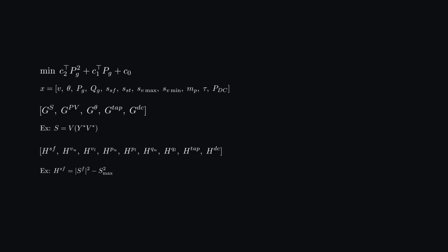By modeling both the active and reactive effects, the ACOPF provides a more realistic picture of system behavior. It can identify when voltage or reactive constraints become the true bottlenecks. It also captures system losses directly, adjusts tap changers or phase shifters to relieve stress, and evaluates how close the system is to the reactive and voltage limits.